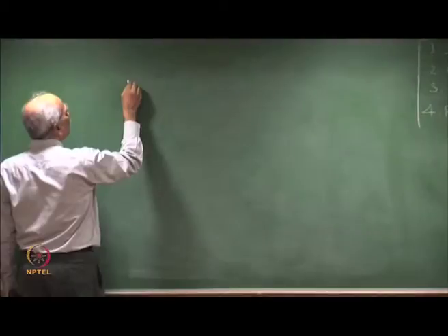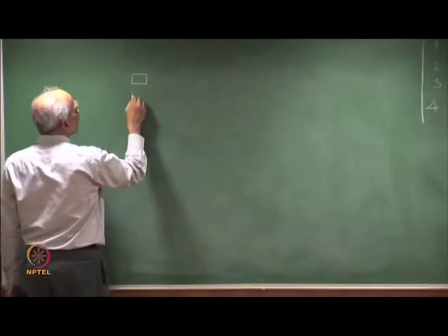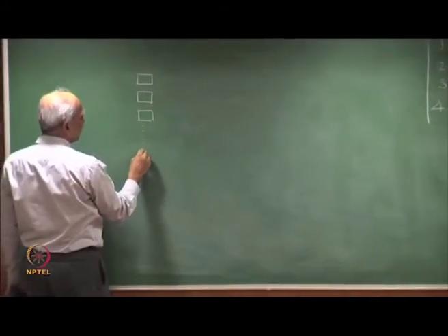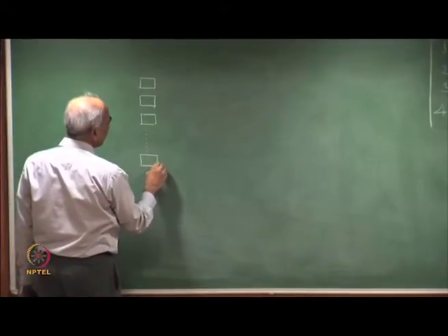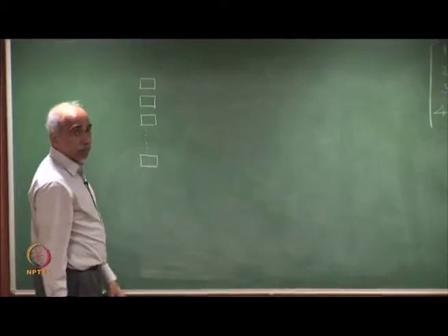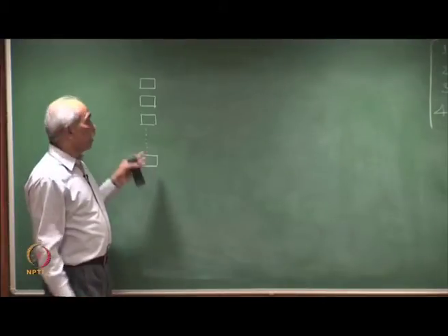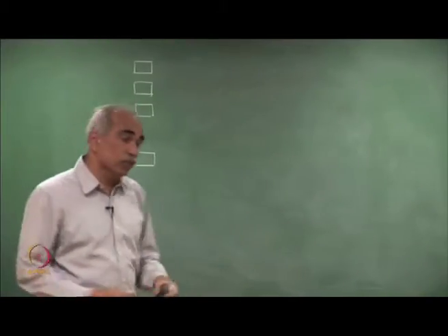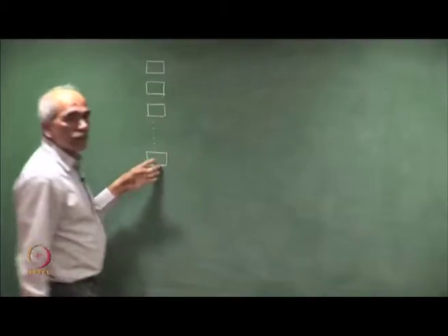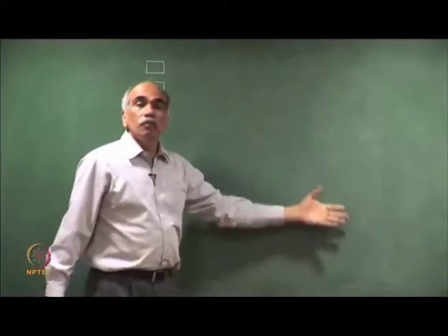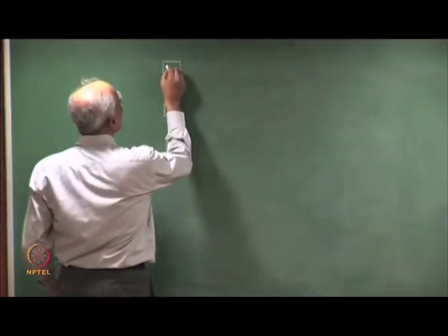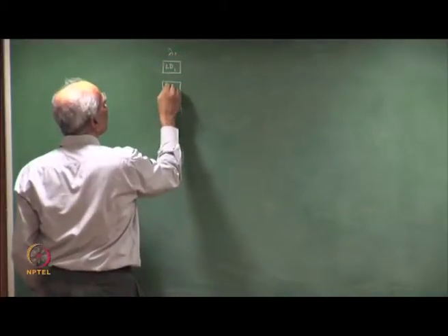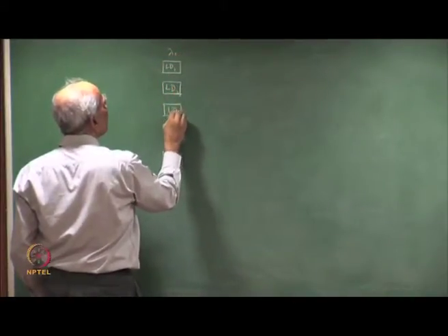So, we have lasers, let us say a 10 channel WDM system or a 40 channel WDM system, could be 10 Gbps. More recently, there has been work reported where 10 channels of 100 Gbps systems were integrated on a single PIC to realize transmitters. So, these are the LD 1 standing for lambda 1. So, this is wavelength 1, LD 2, LD 3 and so on.